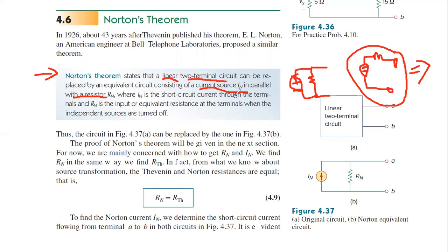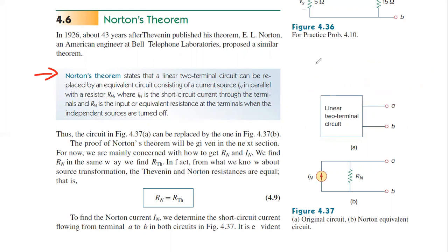Similarly here, Thevenin's theorem equivalent circuit is very similar to the non-ideal voltage source. How is the non-ideal voltage source represented? Plus minus, and this is the non-ideal voltage source representation. This is R, this is V. If I use the same equivalent circuit in Thevenin's, the R will become RTH, the V will become VTH, right? So this is nothing but a Thevenin's equivalent circuit.